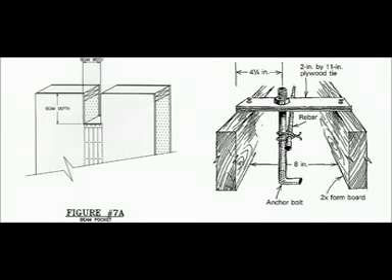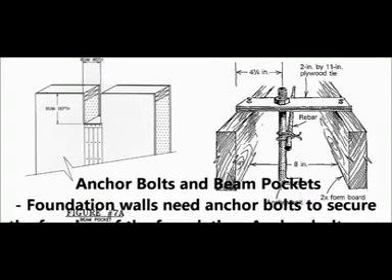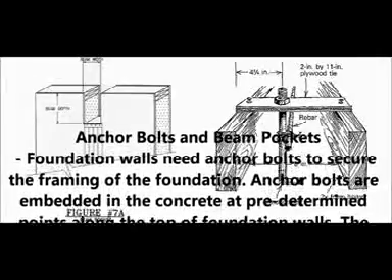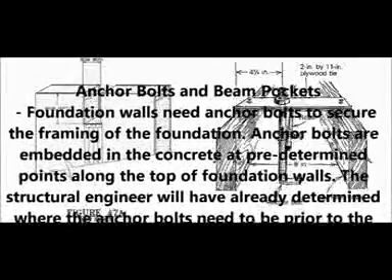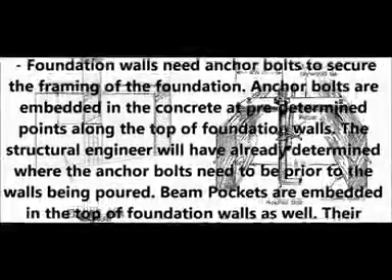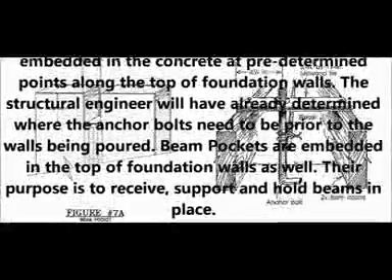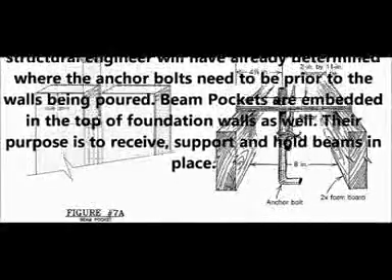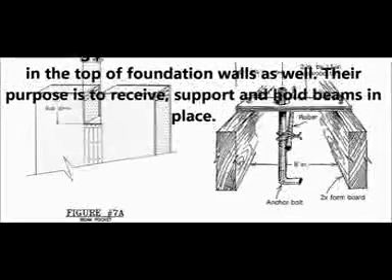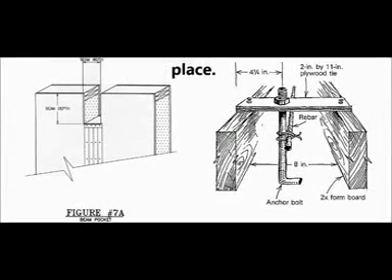Anchor bolts and beam pockets. Foundation walls need anchor bolts to secure the framing of the foundation. Anchor bolts are embedded in the concrete at predetermined points along the top of foundation walls. The structural engineer will have already determined where the anchor bolts need to be prior to the walls being poured.